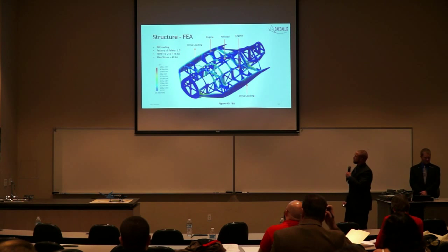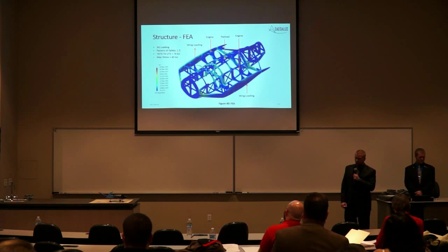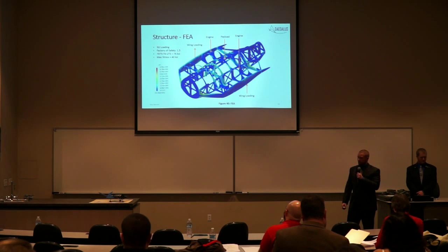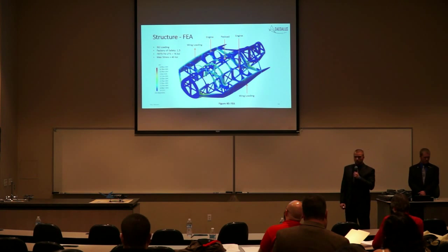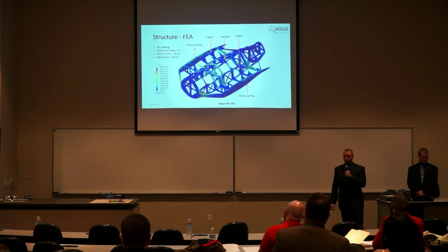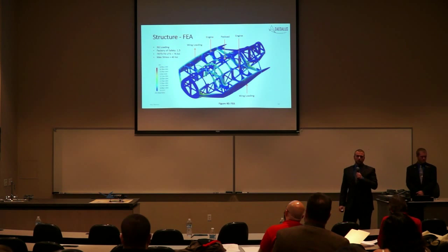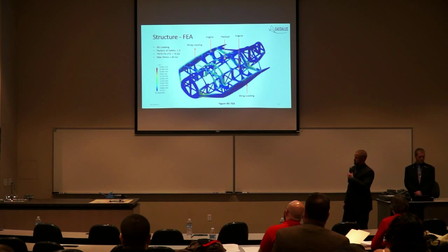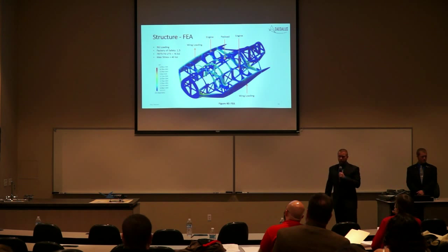In order to mitigate risk, we have performed finite element analysis on key structural parts of the aircraft. Here we have the main body of the fuselage. You can see we modeled both engines, each weighing 4,800 pounds. The maximum payload weight in the bomb bay, 30,000 pounds. And the force of lift at the root of the wing that we equated to the weight of the aircraft.